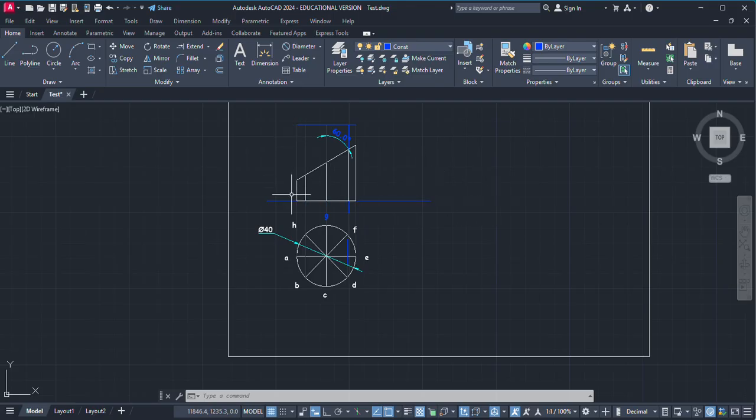And the height, we know this vertical cylinder is 50 mm high, so our rectangle will be 50 mm by pi d. So the length of this rectangle will become 125.6, multiplying pi, 3.14, by the diameter 40.